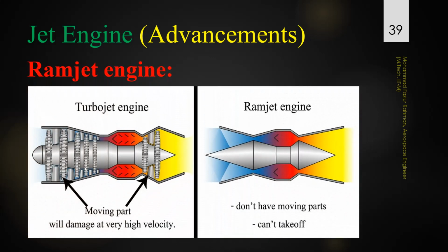We can see a small comparison between the turbojet engine and ramjet engine. You can see that it is very clean and very simple. Just a body to compress the air to do the ram effect, a center body or a spike body, and then we have a nozzle here. Here we have compressors, and many stages of compressors. Then we have some of the stages of the turbine. So it's basically heavy and also causes a lot of loss because of friction. The ramjet is cleaner, but it operates only at the higher speed.